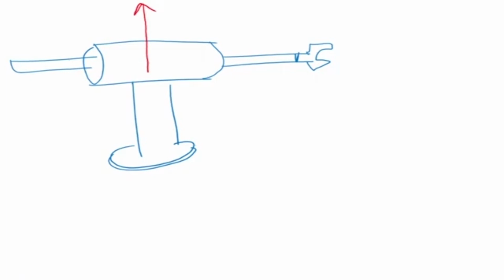Now very often we have to understand this carefully so as to simplify the number of transformations that are required. Okay, so the first axis I'm putting it here. I could have put it here, but if I put it here, what will happen? This additional transformation of the distance will come. Just to reduce it, what I have done is I have put it up there. Okay. So my first axis is my Z0, the reference frame, and the first axis is the first frame. So Z0 and Z1 is the same axis.